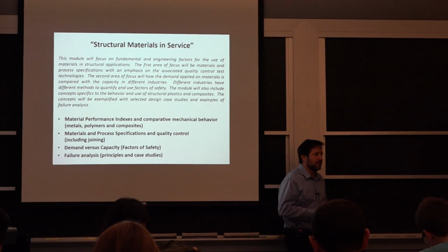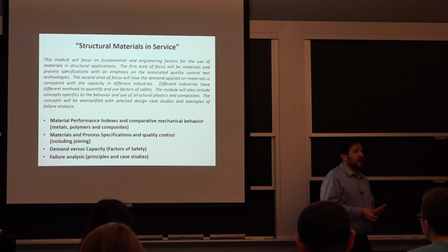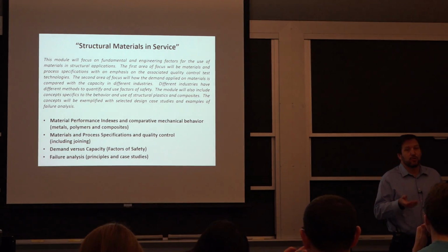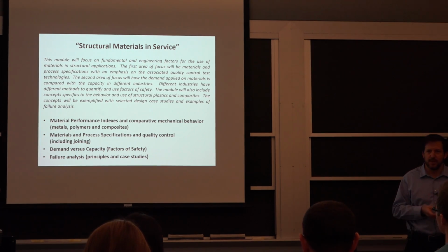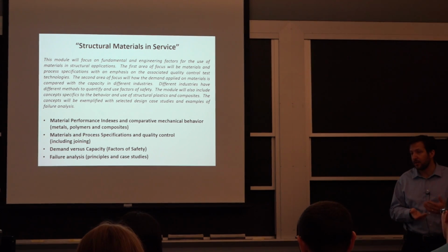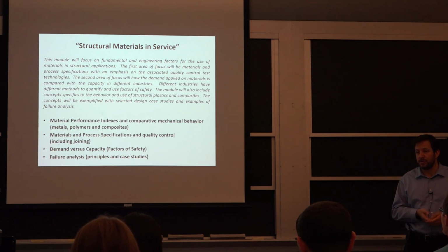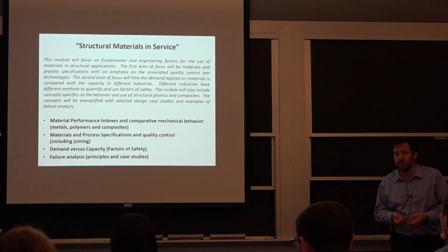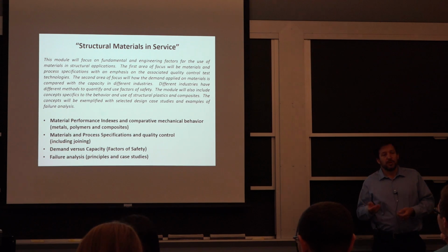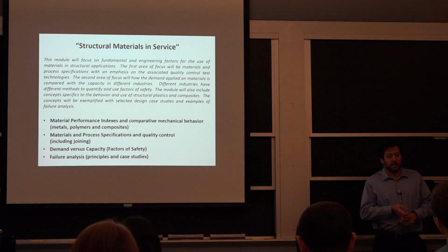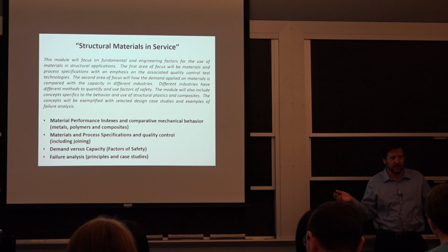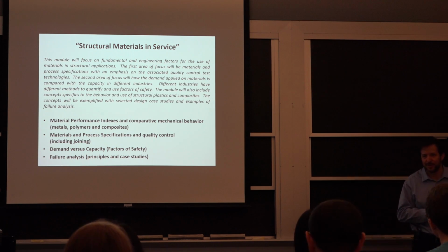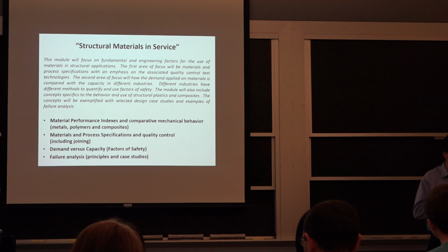Let's say you want to use a steel. You could call it an AISI 1020. So that says the chemistry of the steel, but maybe you also want to have some minimum mechanical properties. In that case, you'd use an ASTM designation, for example. So we'll go a little bit into more details on things that are very important to include, and all of this is with examples. This is probably one of the last lectures that I don't come with samples. I'll be bringing samples to the class and we'll try to go through them.